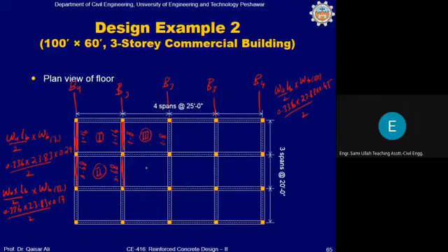See? Similarly, load transferred in the longer direction from panel 4. It will be again equal to 0.336 multiplied by 23.83 multiplied by WB for panel 4, 0.29, divided by 2. How much is the value? 1.16. 1.16 here and 1.16 here.